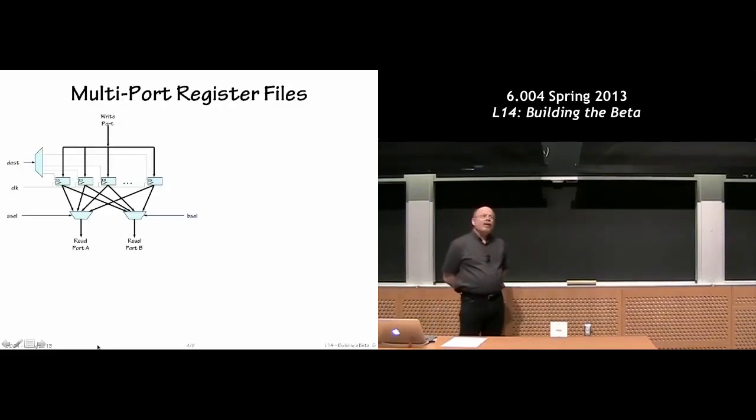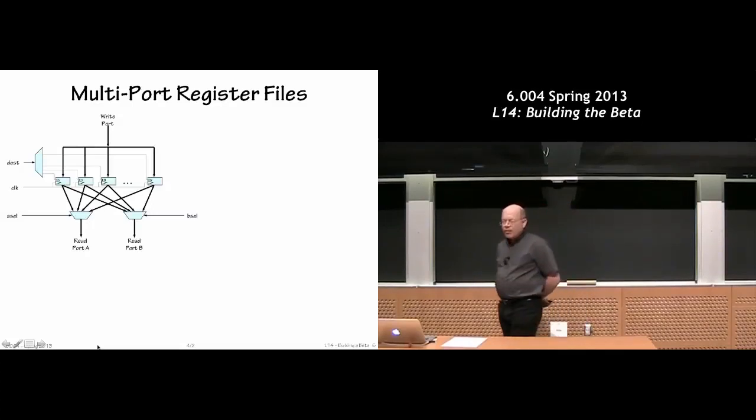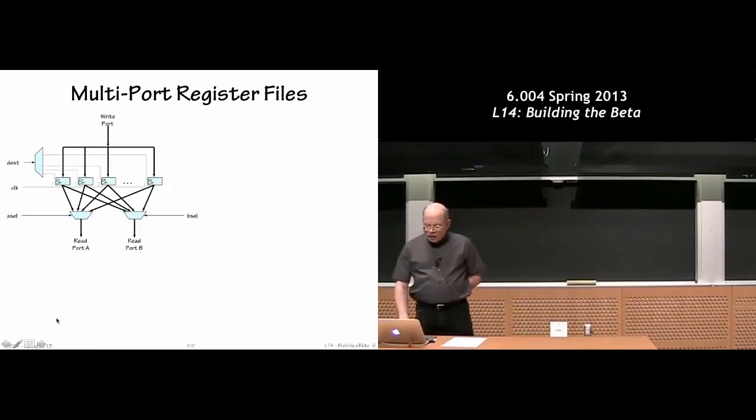Okay, so the first memory that we're going to deal with is our magic little array of these 32 scratch pad registers. They're where almost all the instructions get their operands and write their results. So we actually have this little group of 32 registers. Each one of these little rectangular boxes is a 32-bit register. It can hold 32 bits of information. These heavy lines here are actually 32 signal wires, all coming in, in this case, to this particular register.